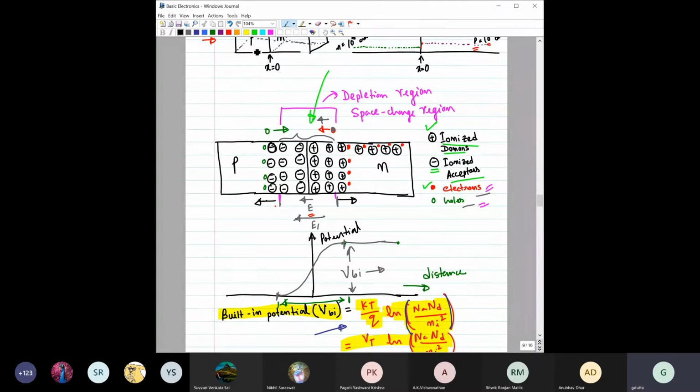See here. So here earlier you have holes, right? These holes now have to diffuse out, right? These holes are coming from this side to this side, and these electrons which were here would move from this side to this side. Okay, right? And so as a result, this part will be left, right? This region will be only left uncovered. So as a result, you will have a depletion layer or the space charge region, right? This part, you have the space charge region, this side, right?